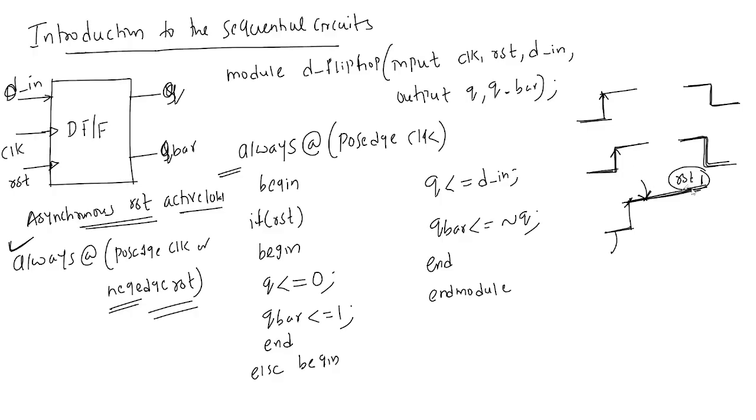Okay, so normally your cell phones are there. When you switch off a cell phone, all the circuits go into reset mode. So when reset equal to 0 only, then it will go to the reset mode. Why do we need extra power, that is, you are giving 1 to operate your circuit in reset mode? That's why we are using active low reset. That is the asynchronous active low reset we are giving.